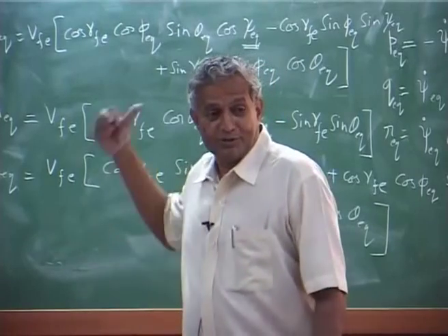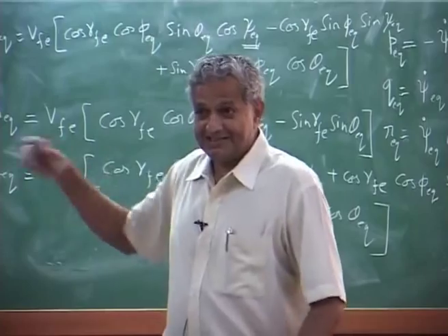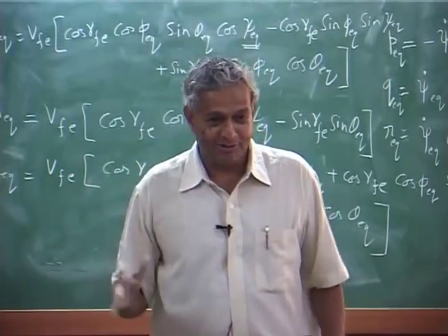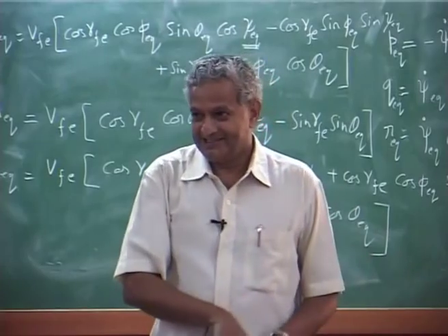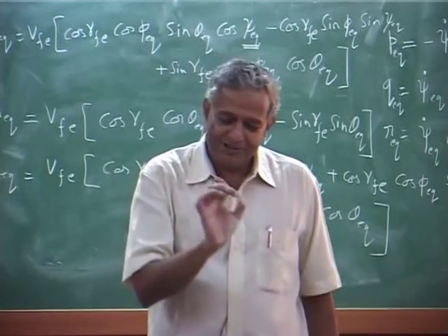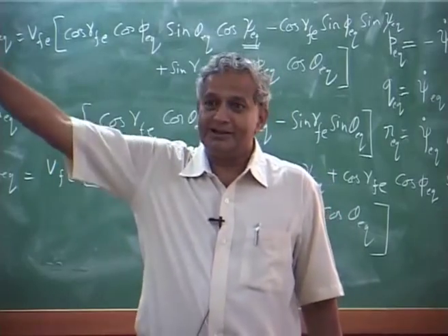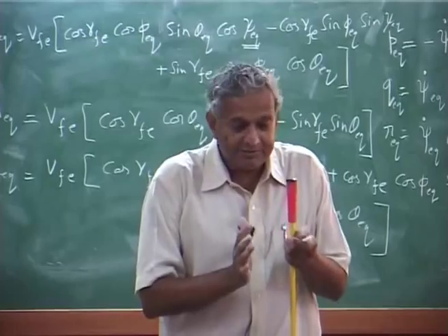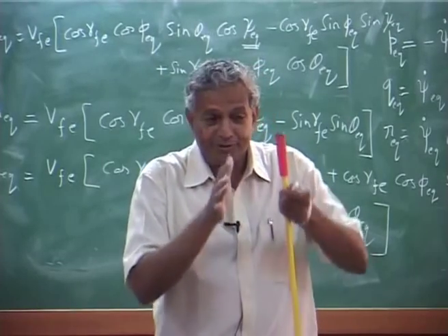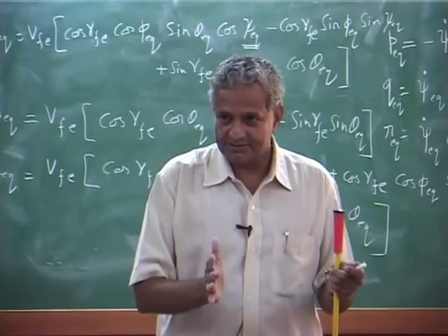You can go and solve my linearized delta u, delta v, delta w equation, that is the perturbation only. Okay. But that will give you only what is happening at the instant. It will not tell you over a long time, because you would have done the equilibrium about a hovering condition and a perturbation about the hovering condition.